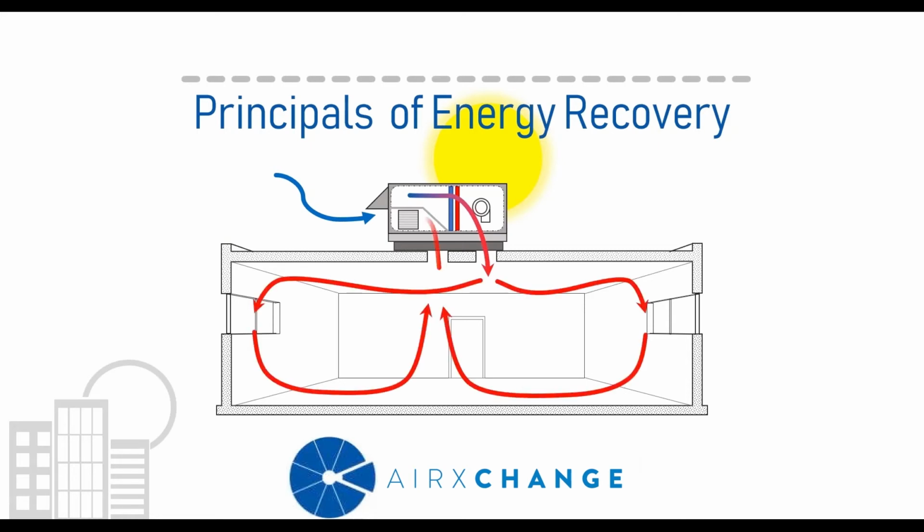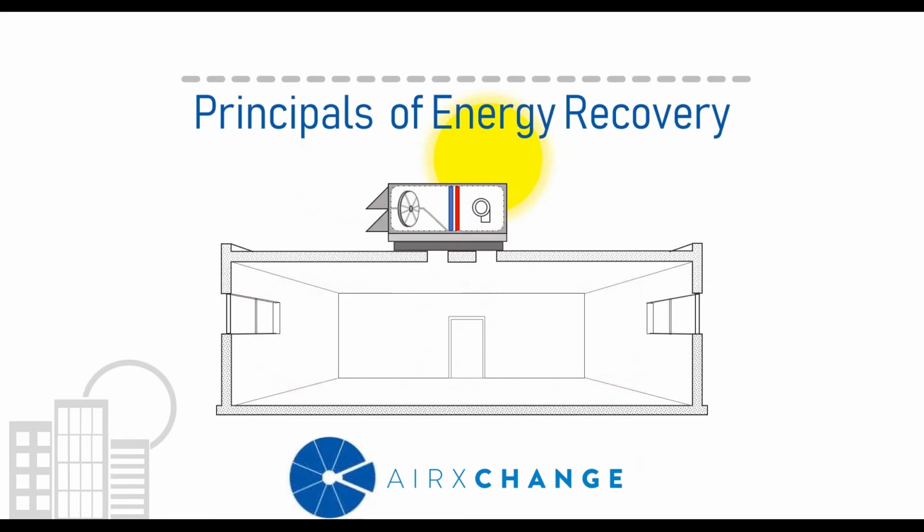And that heated air dilutes the space air with fresh air, and the stale air is then exhausted back through the unit. Now, at this point in the process, the air is typically warm and has picked up a bit of humidity, and you can use that to perform work on the incoming ventilation air.